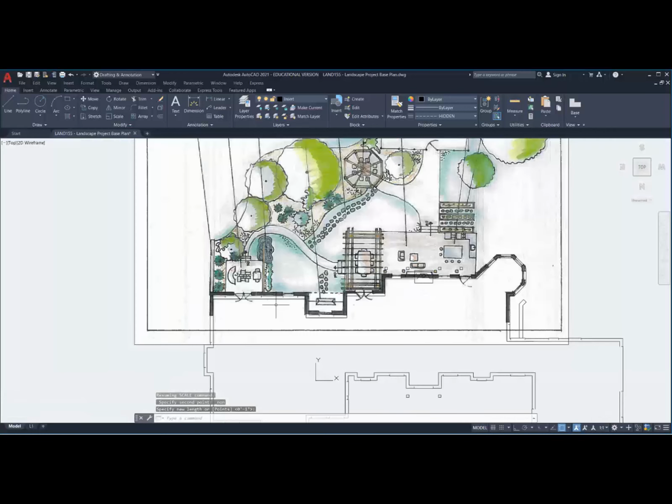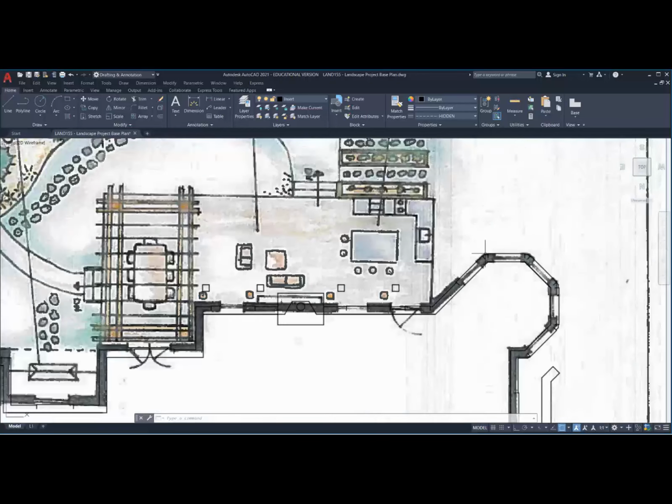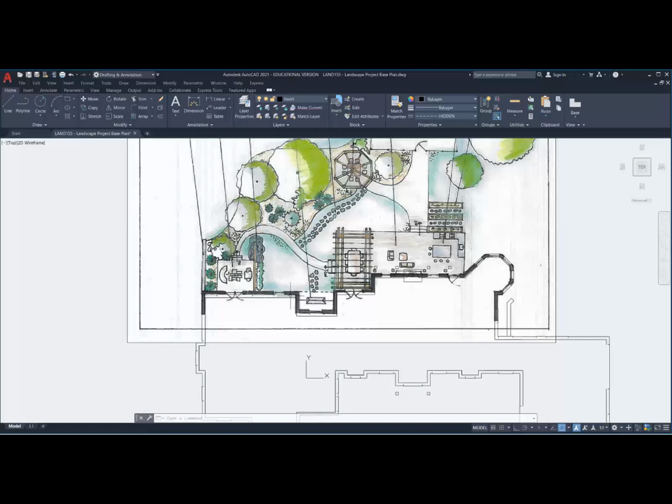Well, almost. The rotation is off. So this point here lines up perfectly. Great. But the drawing, the actual sketch design, is slightly off in terms of rotation. And that's possible just by the scanning process, scanning that image in and bringing it into CAD, and it may not have been a perfectly squared scan. That's okay. So we're going to select Rotate.